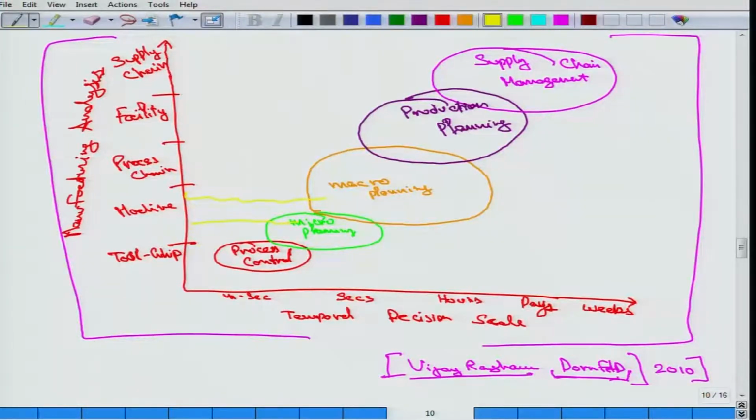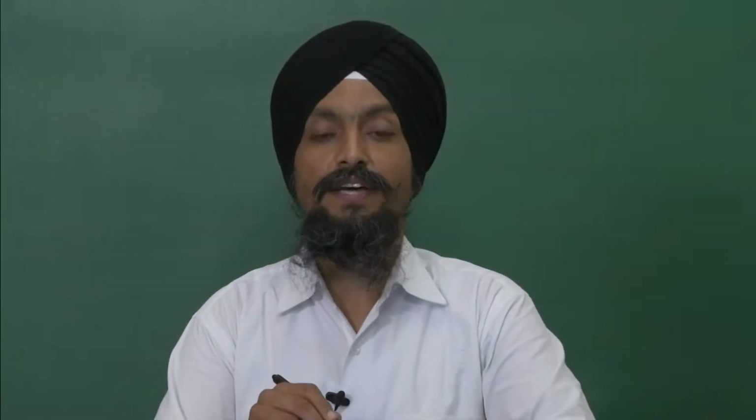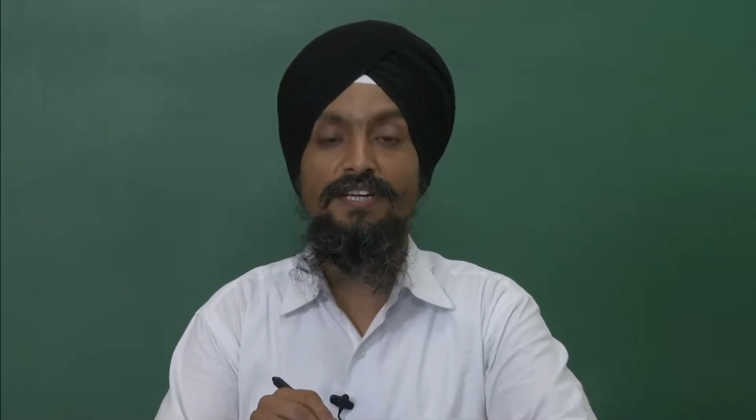Even we would work here on the tool chip interface. So, what are the things that need to be controlled here? What are the factors that need to be controlled? It is the energy. From this point the green manufacturing process starts. We say energy or specific energy, energy per unit volume that is removed, specific energy per unit metal removal rate or per unit depth of cut.